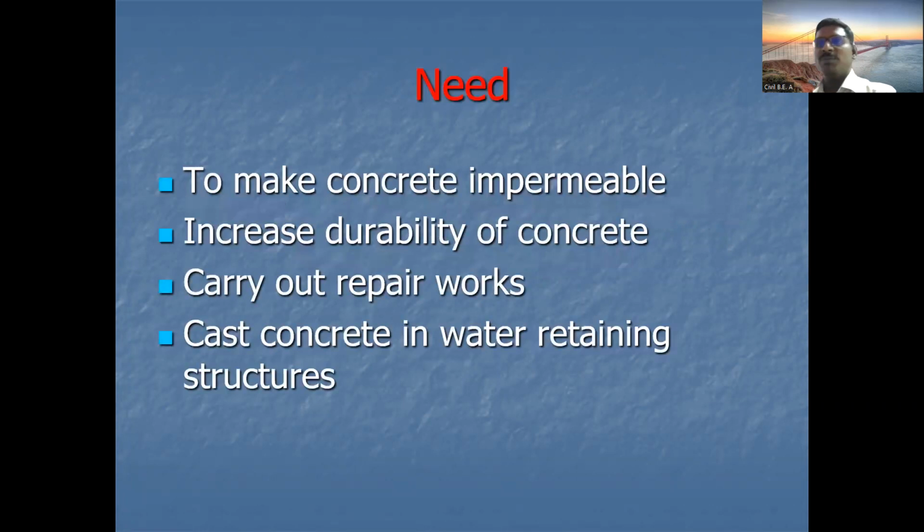So why the need for grouting or damp proofing? To make concrete impermeable, so that water or voids in the concrete are minimized. Why? Because the water seeps through and affects the steel. If steel comes in contact with water, then the steel will be corroded.